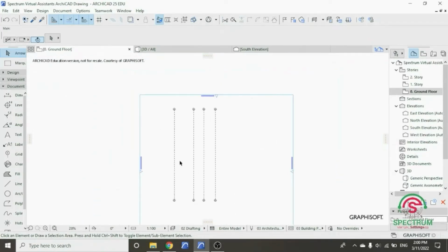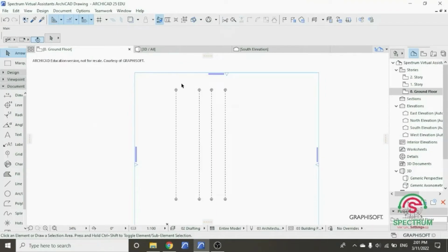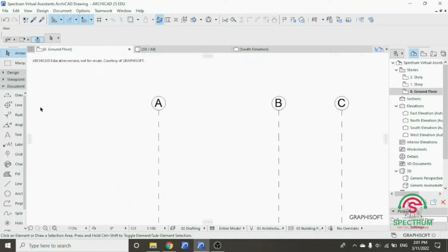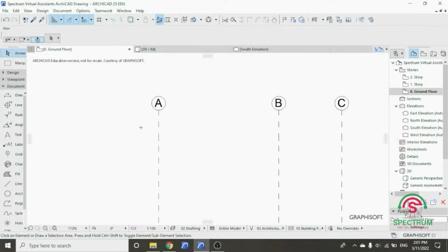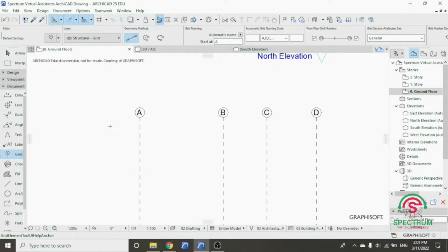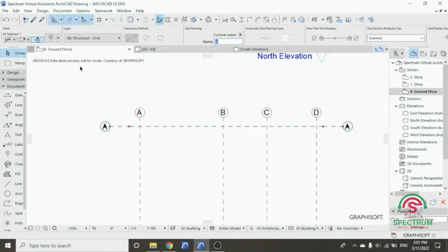Under Documents, under Document, drop down to Grid Element tool, click on it, click on a point in Workspace, drag your mouse and click on another point to end your grid line. Click on the grid line and name it 1.